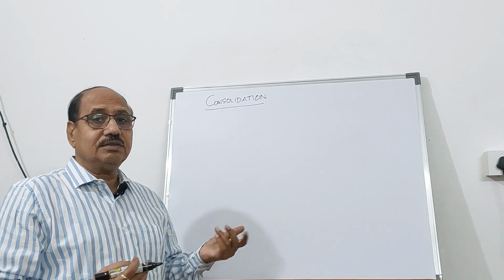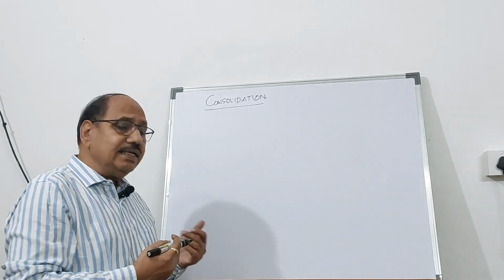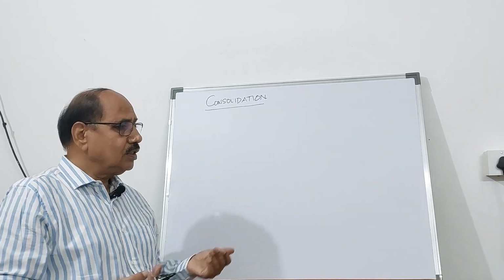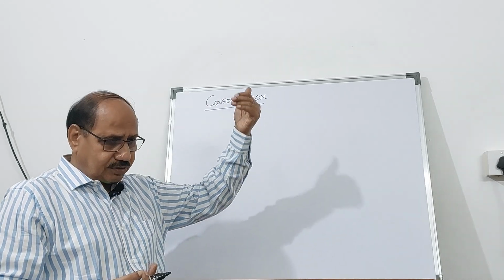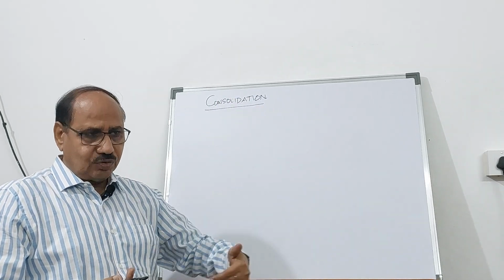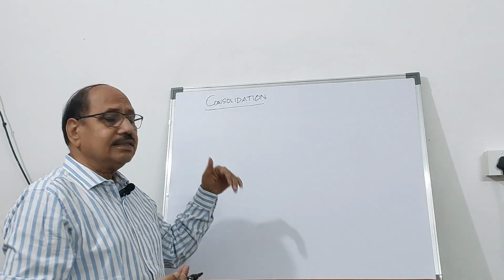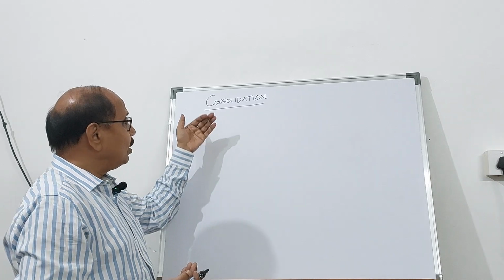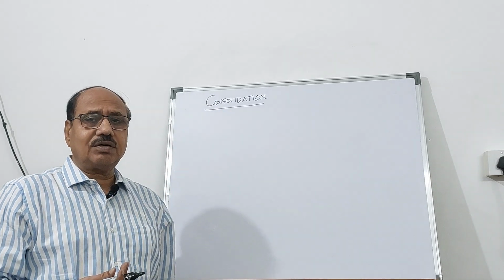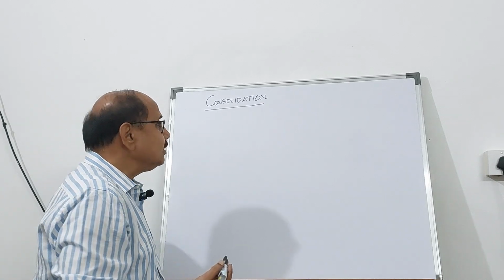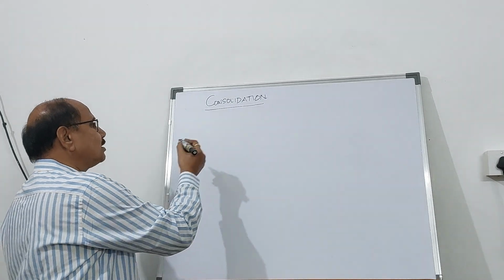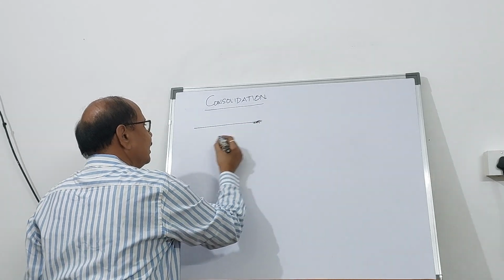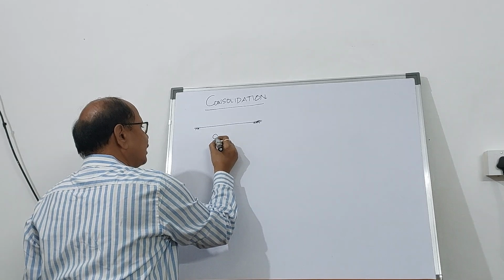And its application is in any civil engineering structure, whether it is a foundation or any other structure, where the load from the superstructure goes to the footing. You will find that the settlement of the soil mass leads to the settlement of the foundation. Therefore, the consolidation process and consolidation settlement is very, very important. So, last time we have seen that there is a saturated soil mass. So, any soil mass which is saturated